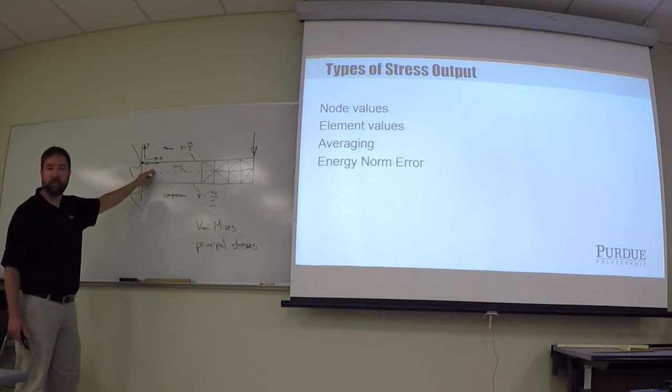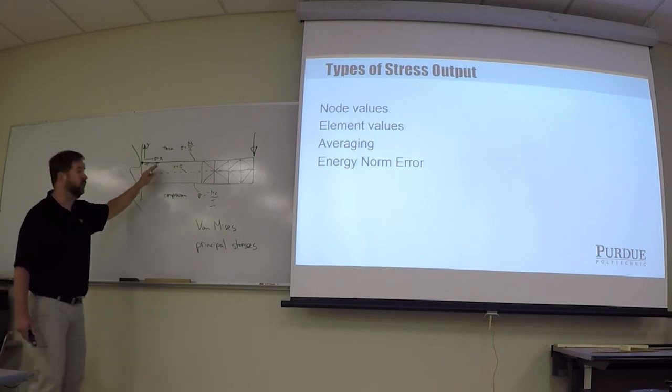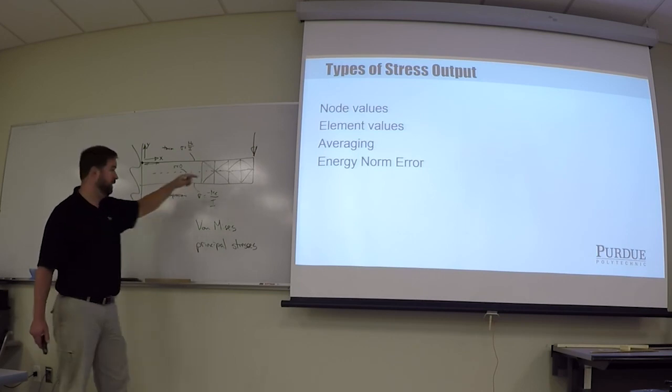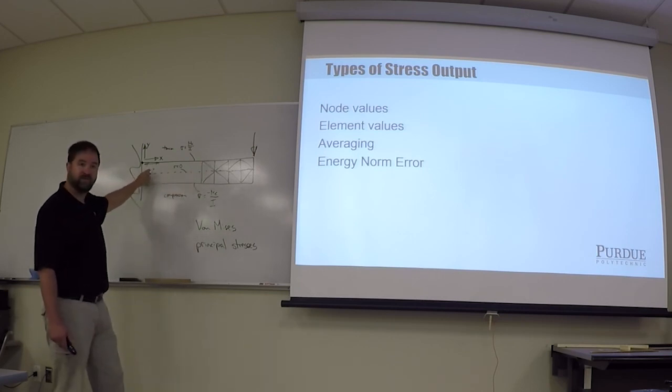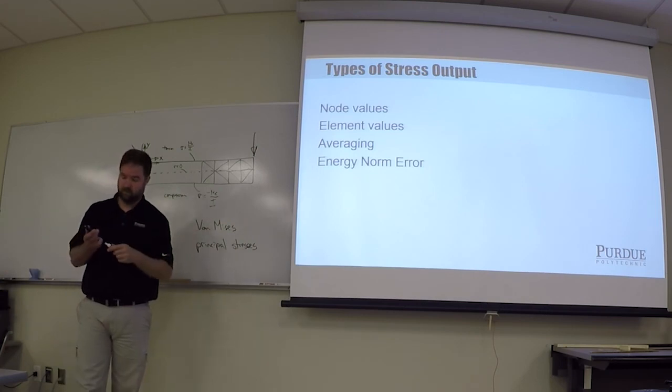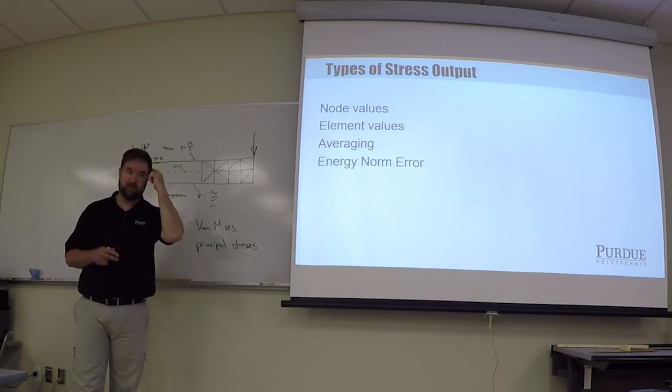So that's a tool that I can use to figure out what's going on if I've got something weird going on. Let's say you accidentally put a force that was in the z direction. You might be getting some y or z stresses, and you're like, where are these coming from? Well, that's an error checking thing. So this can be useful in plotting those different stresses.